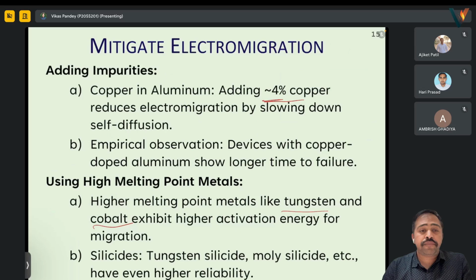That means internally we are flowing current through, say, aluminum, but on top of it we are putting a layer of titanium. So if heat occurs, the upper layer will protect, because it is not going to melt at such low temperatures like aluminum. Even if the line fails, the current might decrease, but it will flow through titanium.